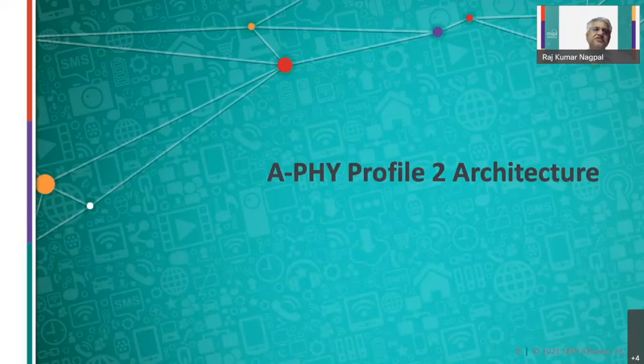By the way, there's a major difference between profile one and profile two. In profile one, for your EMC noises, whichever noises I shared, like static noises or dynamic noises, you have a band pass filter and you have CTLE and DFE to handle and optimize your equalizers, and whatever rejection you need, you have a band pass filter. That's the way you handle it. But profile two, wherein the noise sources are much higher than profile one. Okay, and so here you need to have some sort of noise cancelers.